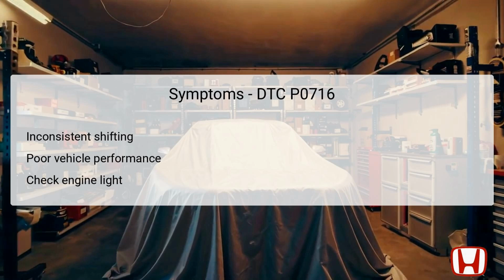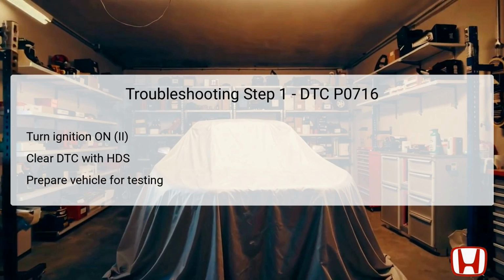The first step in troubleshooting DTC P0716 involves ensuring that the ignition switch is turned to the ON position. This is critical as it powers up the vehicle's electrical systems without starting the engine. Then, utilizing the Honda Diagnostic System, or HDS, clear the trouble code to reset the system, allowing for a fresh set of readings during testing.